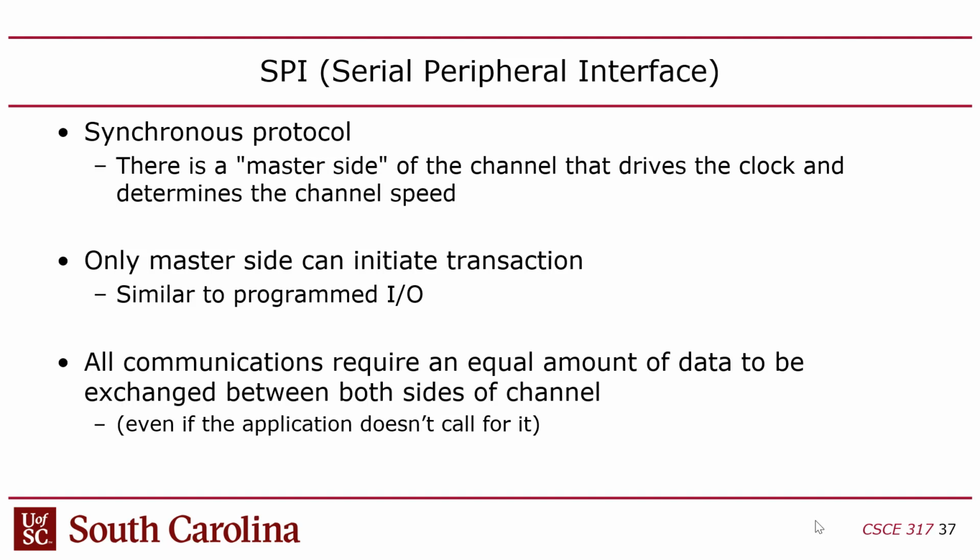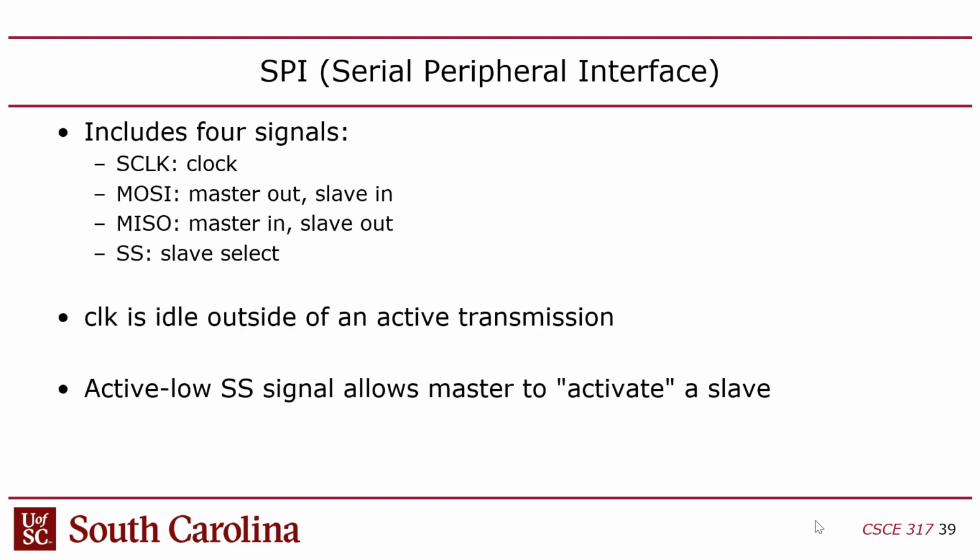And by the way, the serial buses that make up something like HDMI are differential, meaning that instead of 1 bit per wire, there are 2 wires per bit, and the wires switch polarity relative to one another, kind of like how the H-bridge switches the polarity. The reason is that when the wires pick up noise, they pick it up on both wires, and when you subtract them, it cancels out. It's called common mode noise rejection. But SPI and I2C are single-ended, obviously 1 wire per bit.